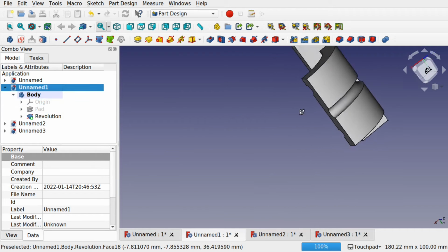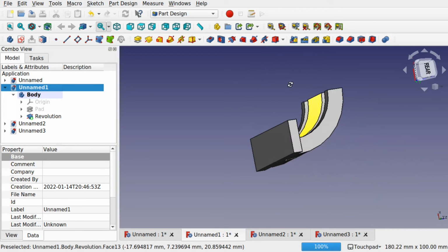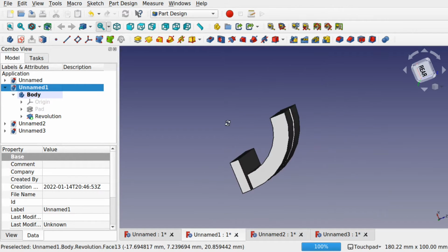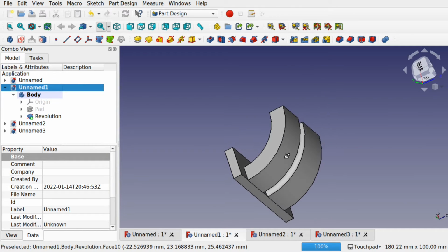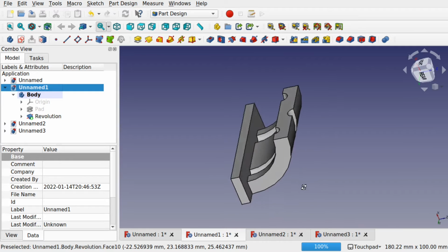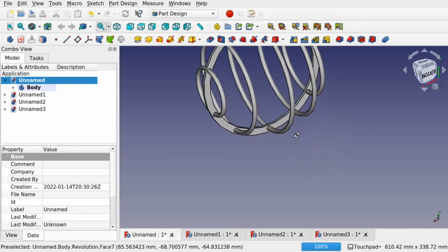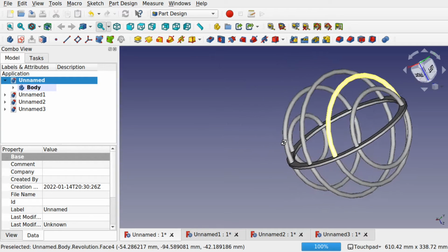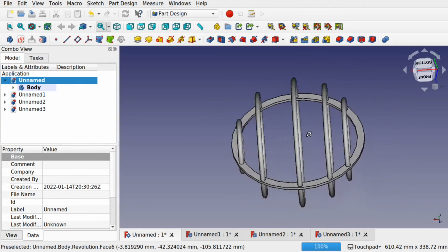We'll be moving on to something a bit different to allow us to create reference revolves. So these are revolves that reference to other parts of the geometry. We're also going to be looking at how to create those revolves that attach to pads and pockets like you see here. Finally, we're going to go a bit left field and look how to easily create such an object as this by use of multi-geometry revolves.